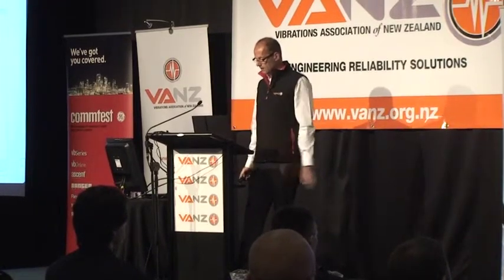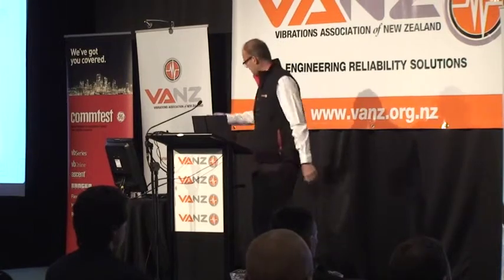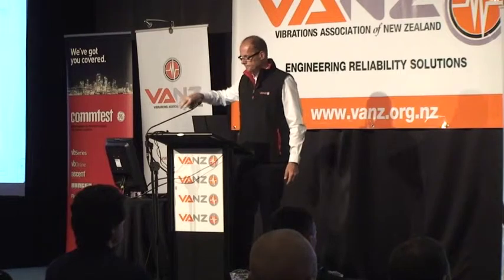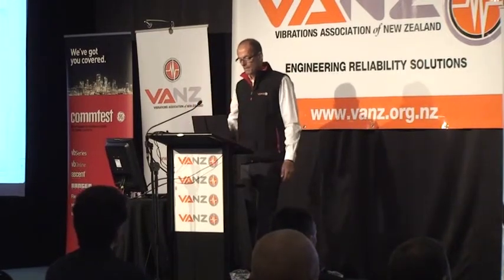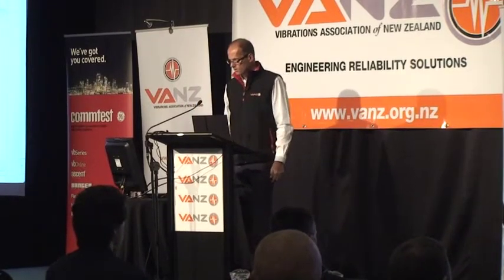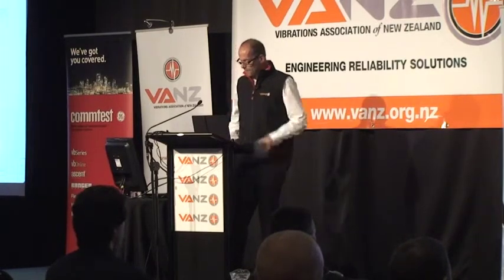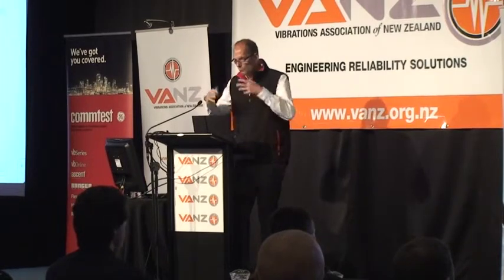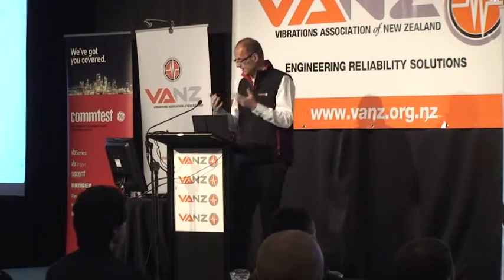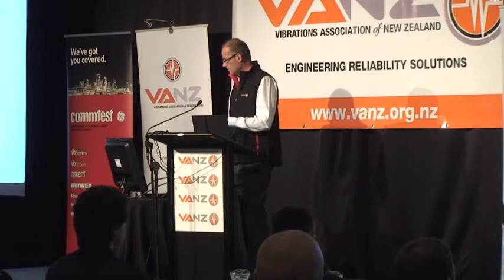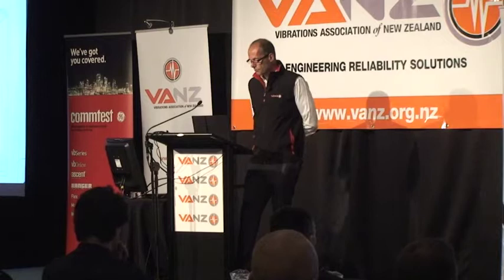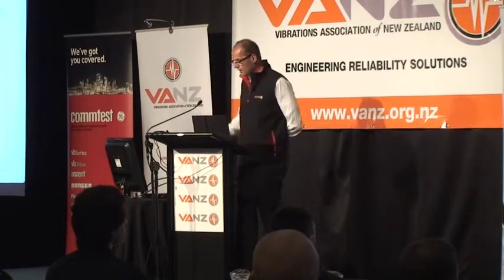In this particular case, there was inner race damage, and you can see that over a period of time, the vibration level increased and then came down when they fixed it. The time waveform changed, as you can see there on the right. But if you look closely at the spectrum at the top, we've got more peaks, and it happens that we've got sidebands. That tells me the damage is on the inner race instead. And when you look at the bearing afterwards, you can see those black lines? That was the damage that was detected.